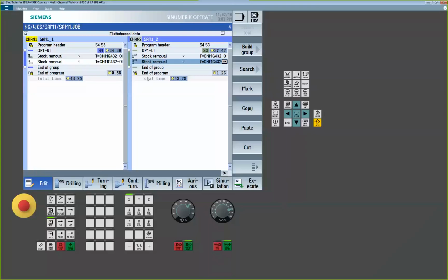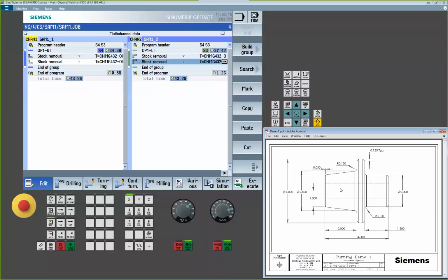Okay, so what I wanted to do on this part, if I look at this part, I've got a hole. I've got a 1-inch hole. I'm going to punch through it, and I'm going to do that while she's sitting in the main spindle for any number of reasons. But for my fixturing, my tooling, my configuration, I happen to want to use the lower turret to do that. So I want my lower turret to run over and go cut on my main spindle.